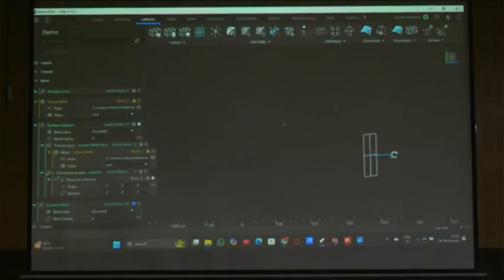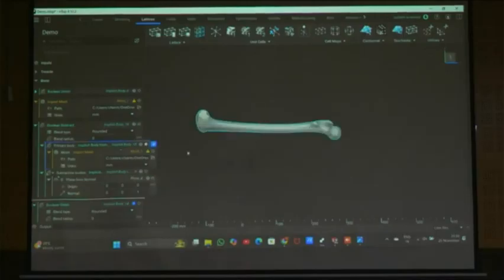See, your plane is here and this is the implicit body and my plane is here. So I need to drag this plane. You can keep it. Okay, we will see how it cuts. See, like this we are getting, right? But I will perform it in one single stroke. I will extract the 3D body.